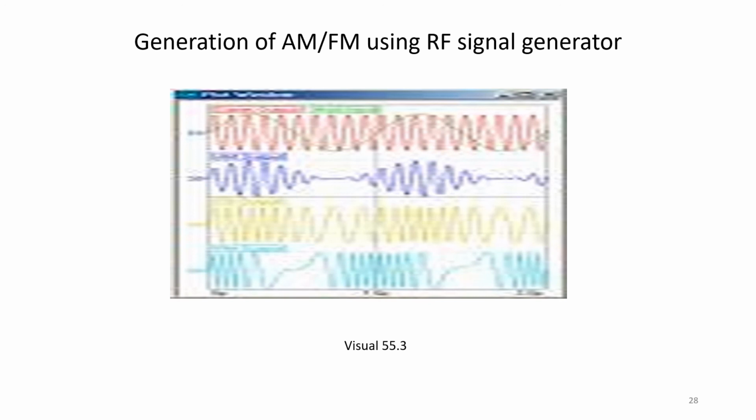and the various applications we have seen: for checking and testing lab equipment, for troubleshooting the electronic equipment, alignment of radio and TV receivers, testing of amplifier response by varying the frequency of the RF signal generator, which can be given to an amplifier as input. You can check the output by varying the frequency at the input of the amplifier.